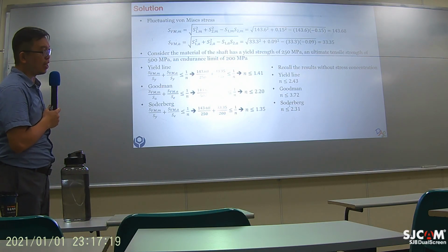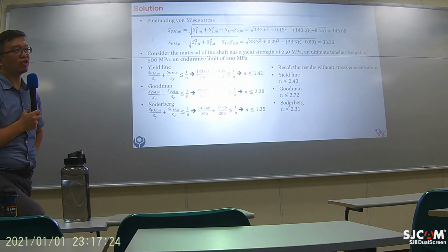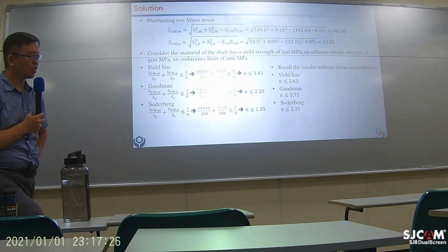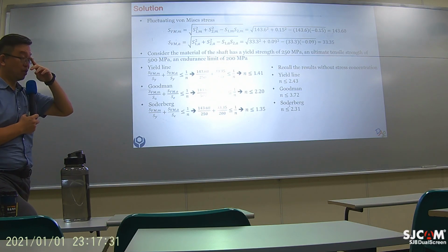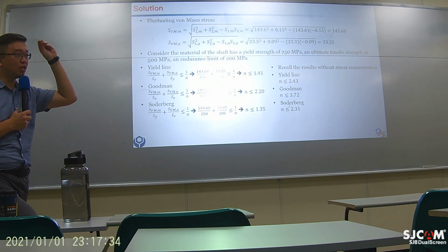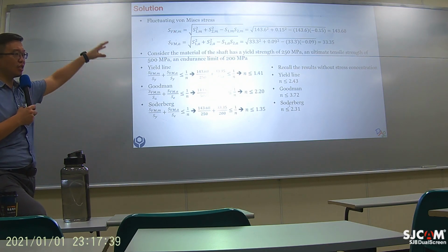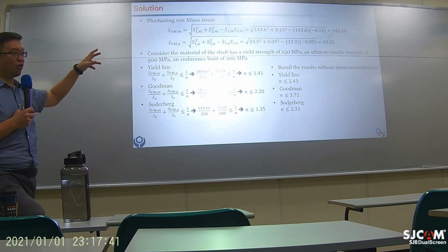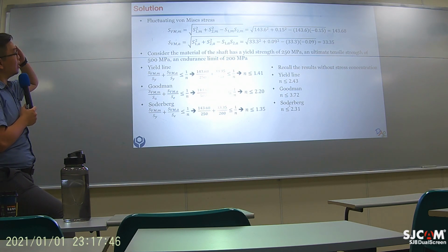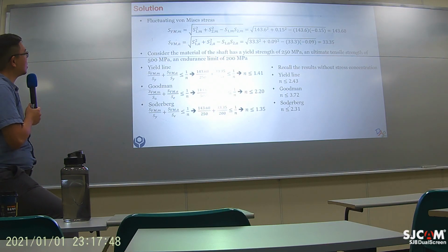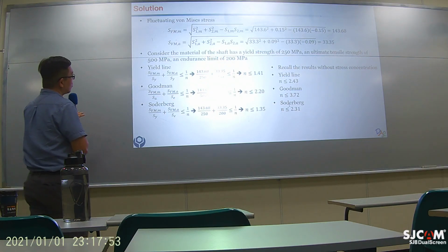And over here, they are already including the consideration of stress concentration effects. Because when you compute the principal stresses, you already apply the K values. So now in this design equation, you are already considering stress concentration. Just plug in, and then you get some answers on the right. And use it for the design equations for fatigue.